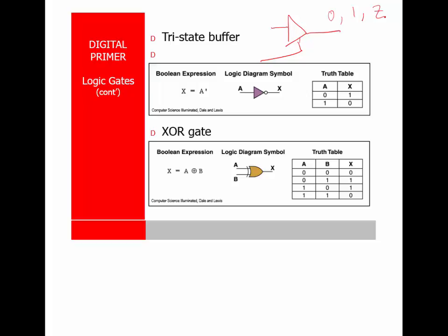You have to go to the next faster set of chips. All of a sudden the thing quits working again. It starts having malfunctions. And the problem is these timing glitches start popping up. And in worst cases, you have to go back and totally redesign the circuit. So sometimes you'll find a buffer used just to put in timing delays in order to prevent these glitch problems, but most of the time it's for current amplification.